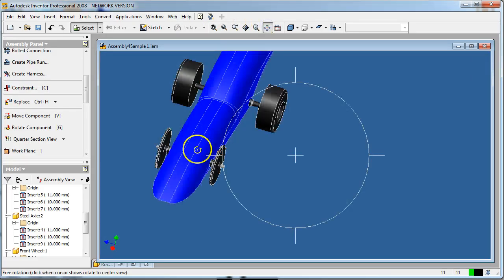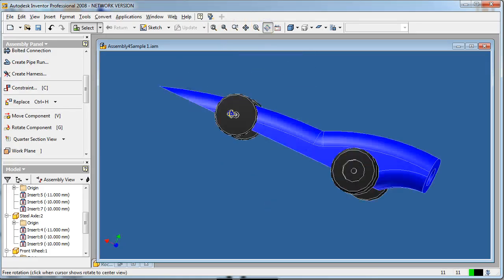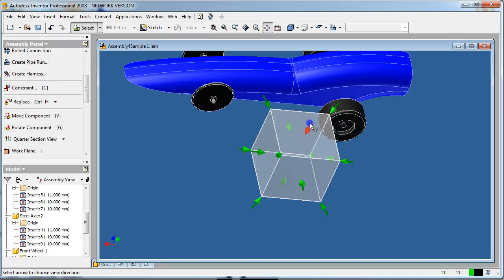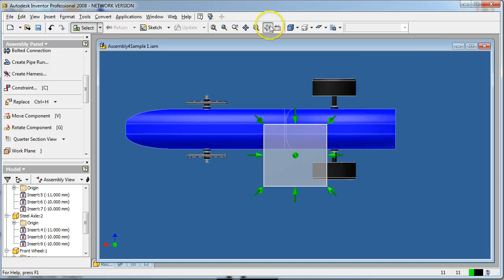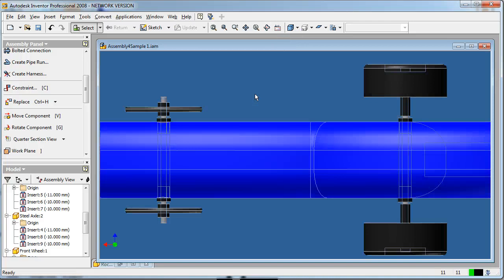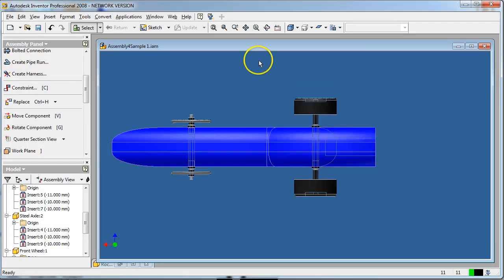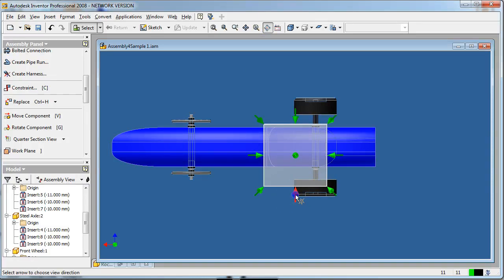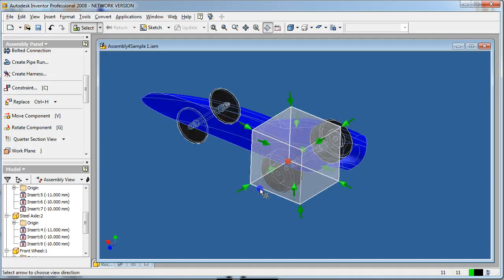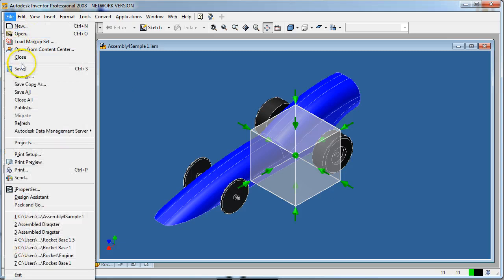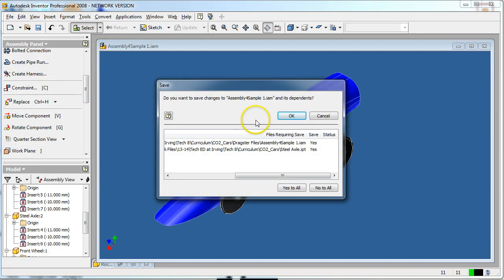So here you look. There's your finished car. Last thing I could do then is to rotate it so that we're looking down on it. Aerial view, the top view. And we're going to go into the hidden view, hidden lines. Everything looks good, ready to go. And that is a completed, assembled drawing. So rotate it back if you want on an isometric view. Pull it back into no hidden lines. And from here, save it.